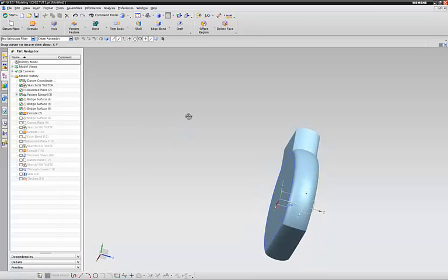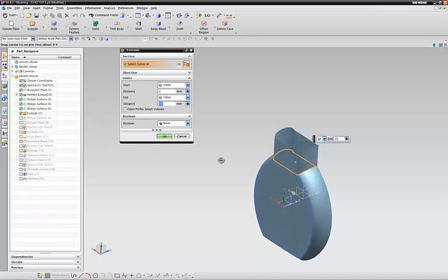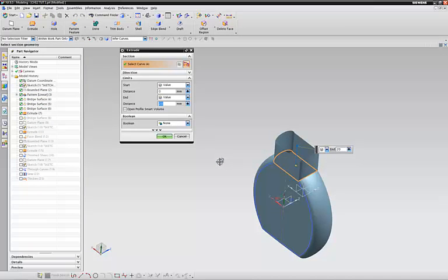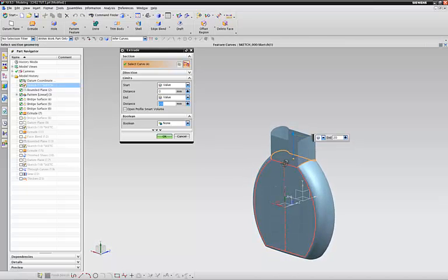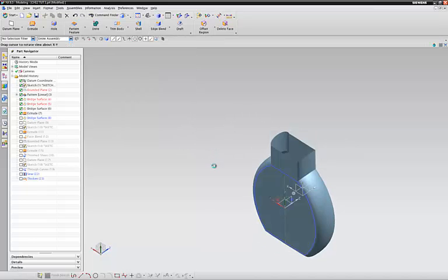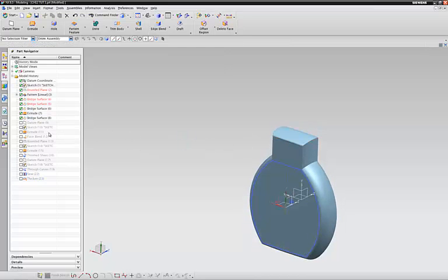Here's where I put in an extrude. This was kind of tricky. Heads up, it depends on which surfaces you click first and the direction it's set before it will select everything. So I selected this edge and then that far side, made sure it was extruding up, and then added the two others, the rounded edges. And then it attached itself. Put in another bridge on top of that.